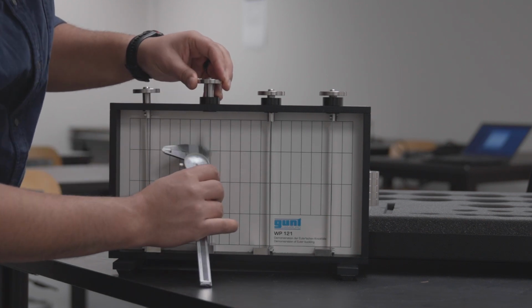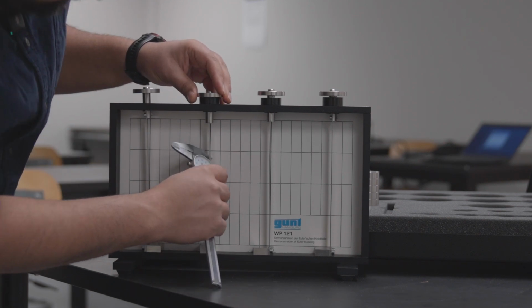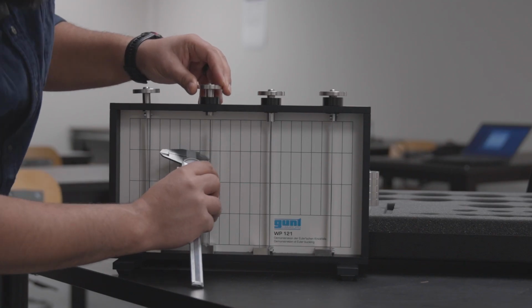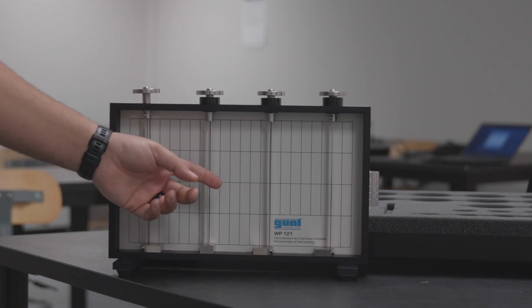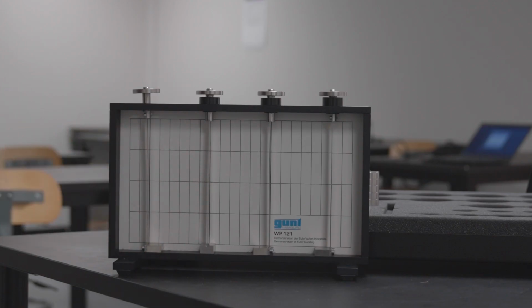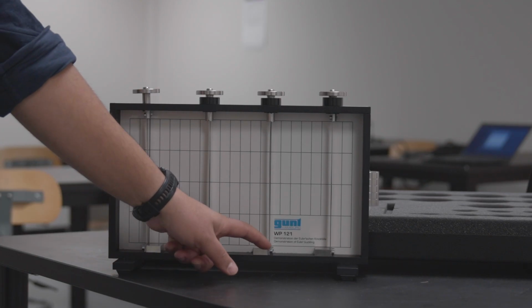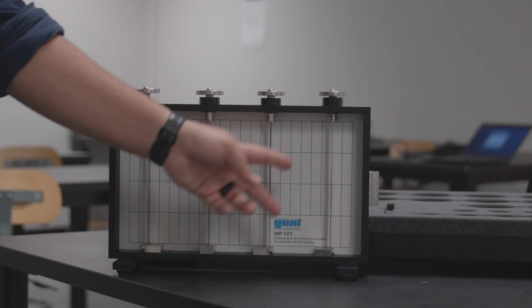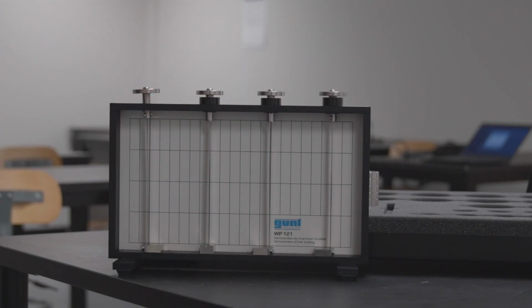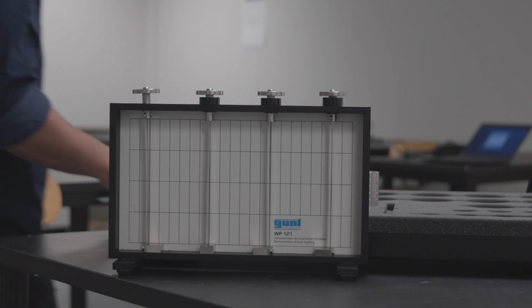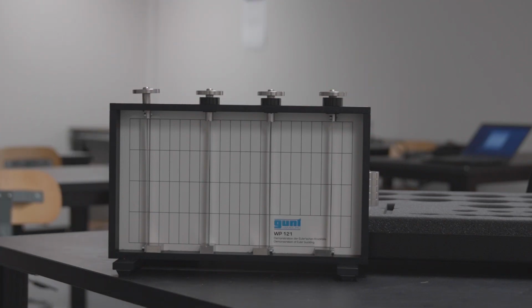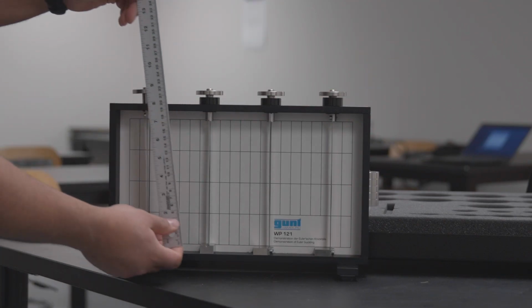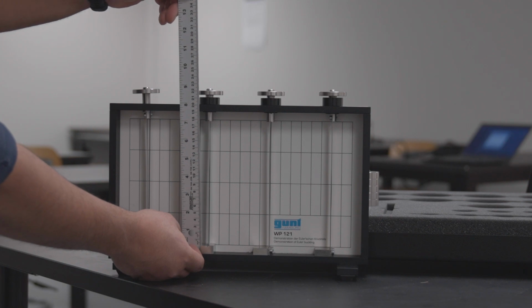The next step would be to take the measurement of the length of the column. The measurement of the length needs to be from one support to the other support. So it is not the full length of the column, just one support to the other support. You will be given a ruler or a tape measure for this. This ruler can be used for vibration as well. Then you can make your measurement right here.